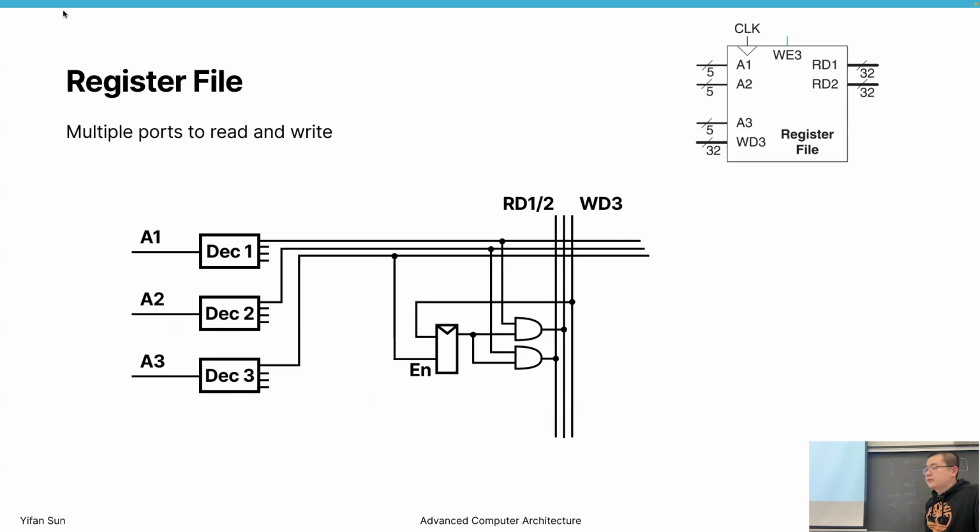We still want to use SRAM. So in this case, just consider this one as an SRAM 6T unit. Okay, in this case, we do this. We have multiple word lines and multiple read and write lines. These are bit lines. Those are word lines. Those are address inputs. Now we first have a decoder, and the decoder is connected to these lines. Just consider it almost 3 independent input and output logics.